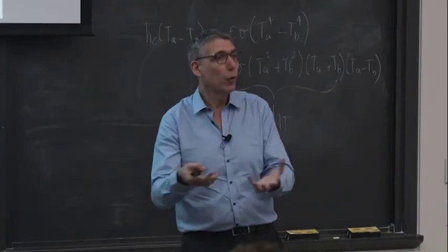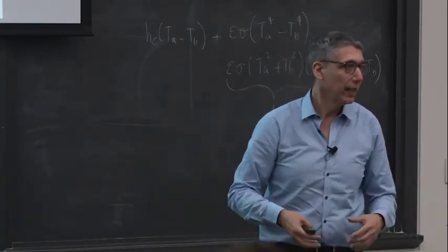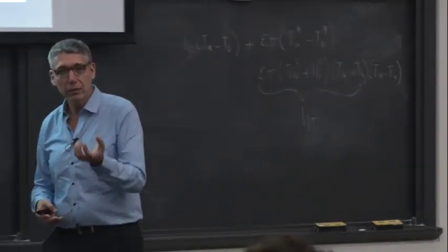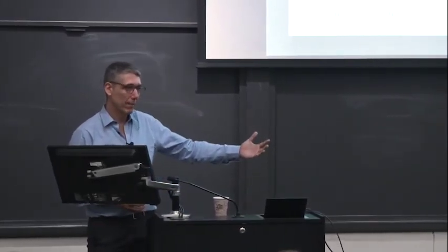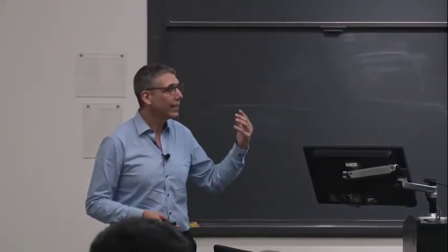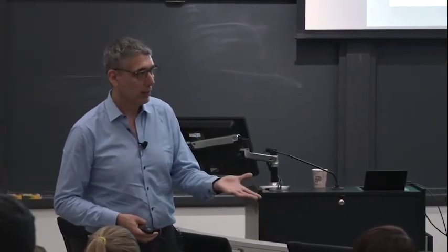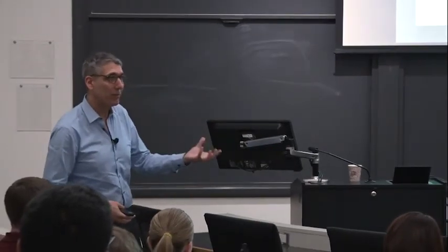It's not a brute force test like what we saw with BS 8414 or NFPA 285. Remember the big test where you put a crib and you burn it and that's it, pass or fail? No, this is a test that has very thorough fundamental physical principles. And these principles are presented in a way that is so elegant that it delivers everything you need to get a sense of what matters, what dominates the problem. Now, clearly, it is a simplification, and this was done in the 1970s. The purpose of it was to give you physical insight. It was not to use it as an input for a CFD code. He never thought of it as the input for a CFD code. He thought, I'm doing this so you understand what matters.